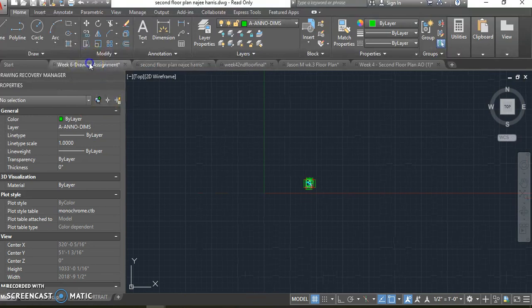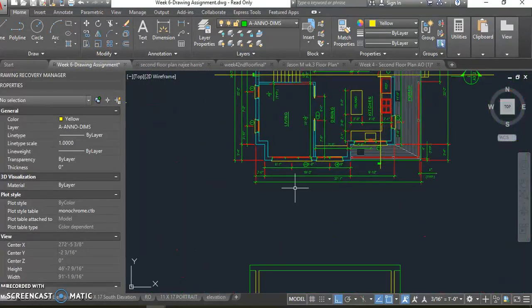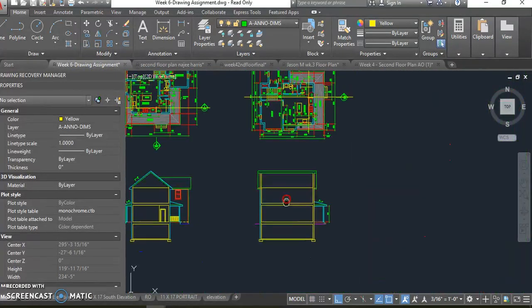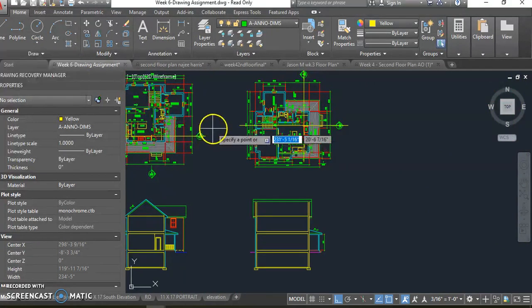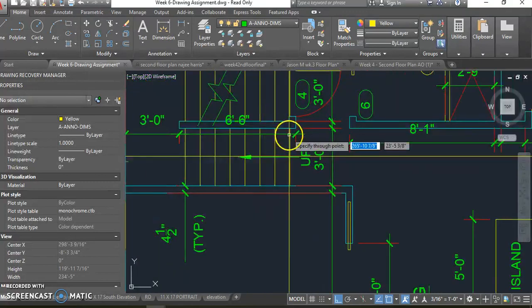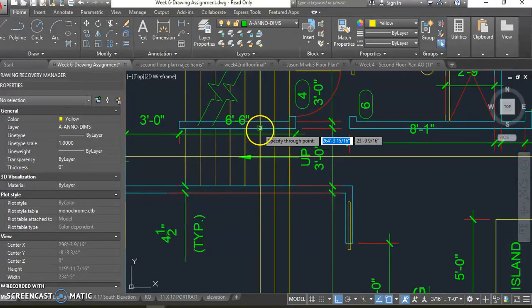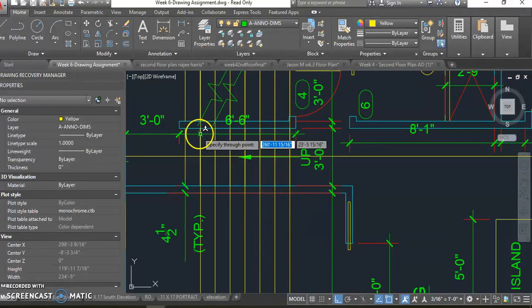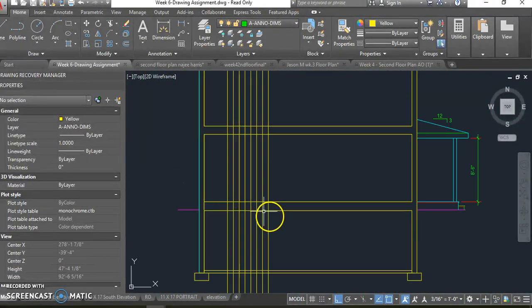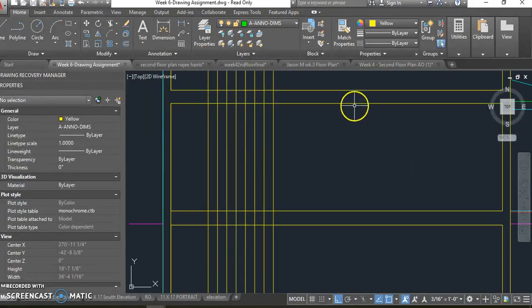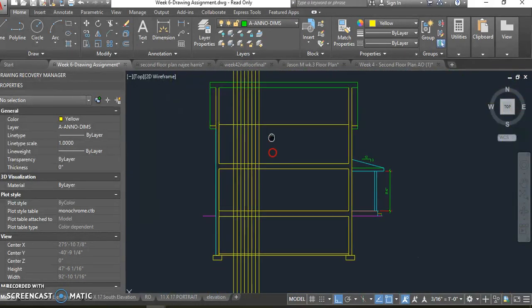Let's see. Here we go. So, I'm doing vertical construction lines. Right click, vertical. And I'm going to place one at the bottom of the stair. Actually, I'll just do them all. I'm going to place construction lines for every one of these tread lines until we get to there. So there's my staircase. It starts here. And then it goes up however many risers.